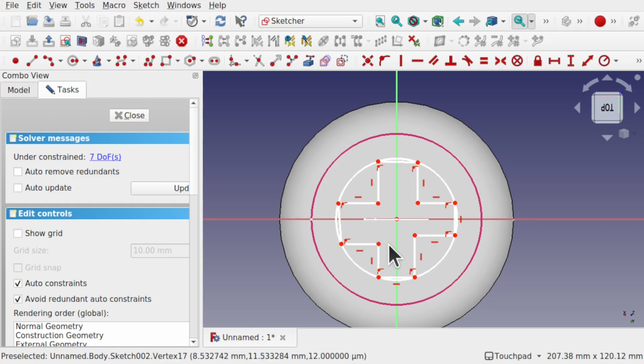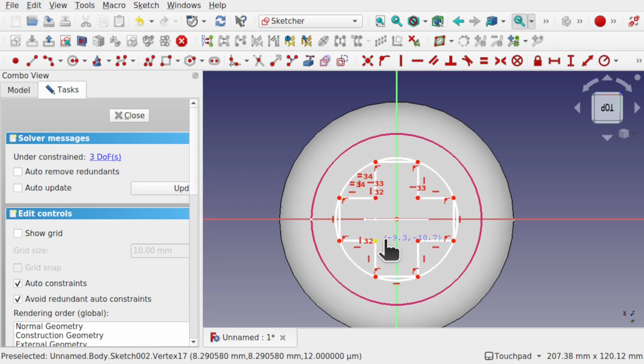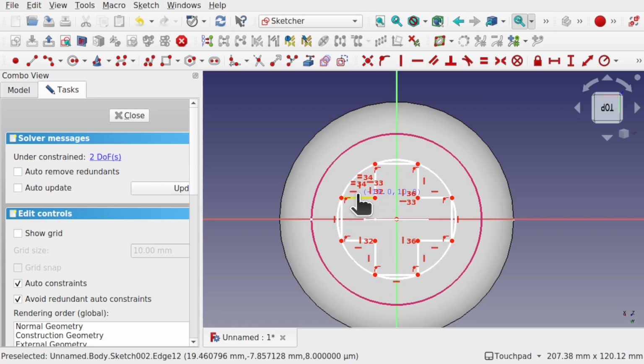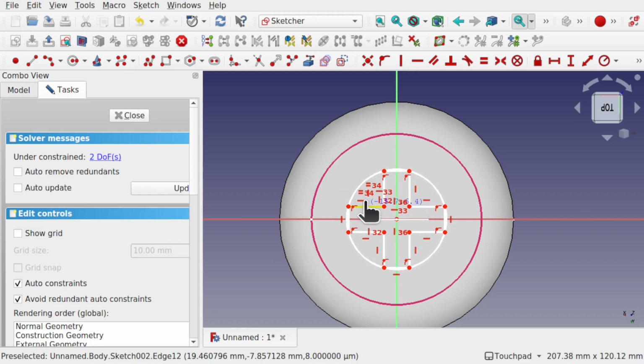And now we need to create some inline constraints. So these 2 are in line, and these 2 need to be in line as well. And using the equality, so we take this one and make those equal. And this one isn't vertical, so let's add a vertical constraint there. So we've got movement like so, but we need to make sure that these 2 are in line as well. And let's have a look, see what we've got. So we've got a nice cross in there.